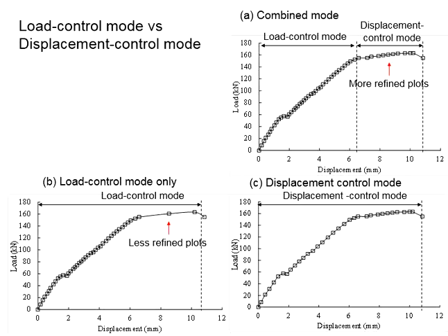Now your reading at the early stage depends on a certain load interval, and then as the displacement accelerates, readings are taken based on the interval as defined by the displacement. This will give you a more refined plot when the displacement increases rapidly.